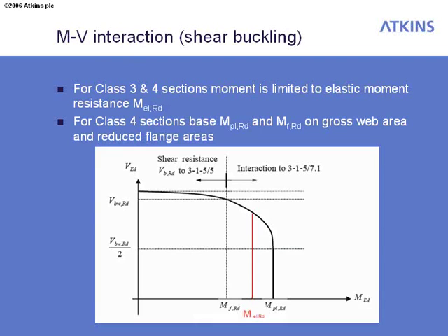So it is really a very useful tool for getting that extra bit of capacity out of something. And we found it particularly useful for assessment and strengthening schemes, where you've found you need a whole bunch of extra stiffness to strengthen up a web in an old box girder or something. You start applying these equations, and suddenly you can get rid of a lot of the interaction requirements, and you can therefore reach a point where you don't have to do nearly as much strengthening on the section. So clients quite like you using this sort of stuff.